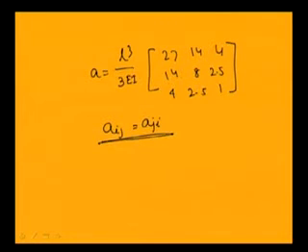That means A21 equal to 14, here A12 is also 14. Similarly A13 equal to 4 and A31 is also 4. Similarly A23 equal to 2.5 and A32 also equal to 2.5. So you can observe that Aij equal to Aji. This is known as the reciprocity theorem.